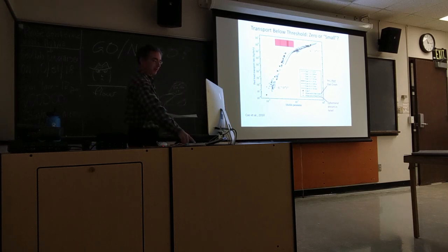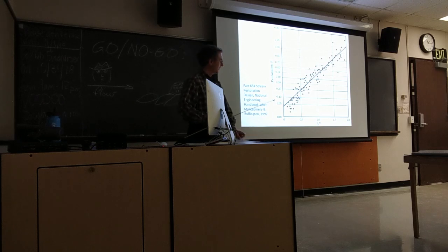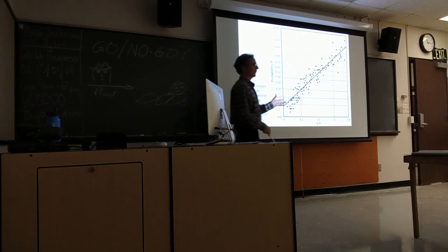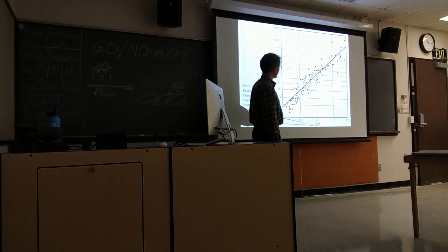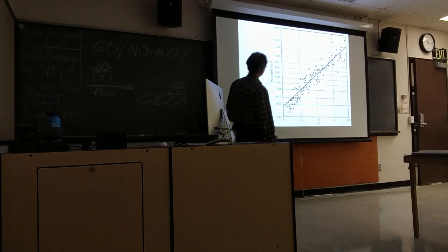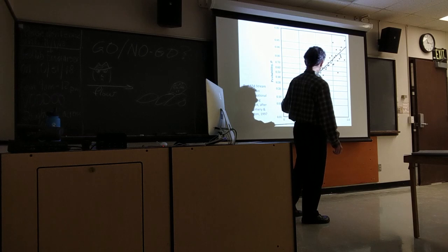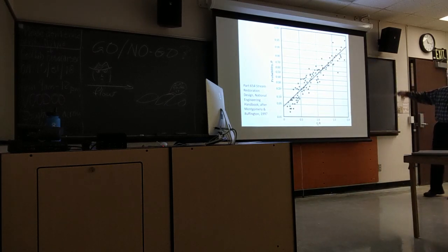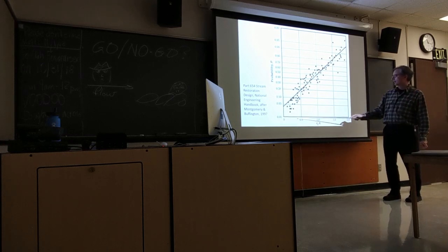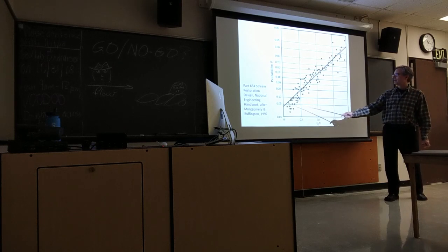Now that's why engineering manuals are more going to graphs like this that say, okay, this is more about the probability that something's going to move. So this is from a stream restoration design manual, and here we've got the so-called critical value of shear stress, this is dimensional, divided by the actual shear stress. So that's saying, well, this is the probability, oh goodness, I think it's the probability that it doesn't move. Okay, yeah, if the critical value is twice the shear stress, then there's like a 95% chance that it won't move. Whereas if I'm down here where the critical value is less than the shear stress, then there's a decent chance of motion.